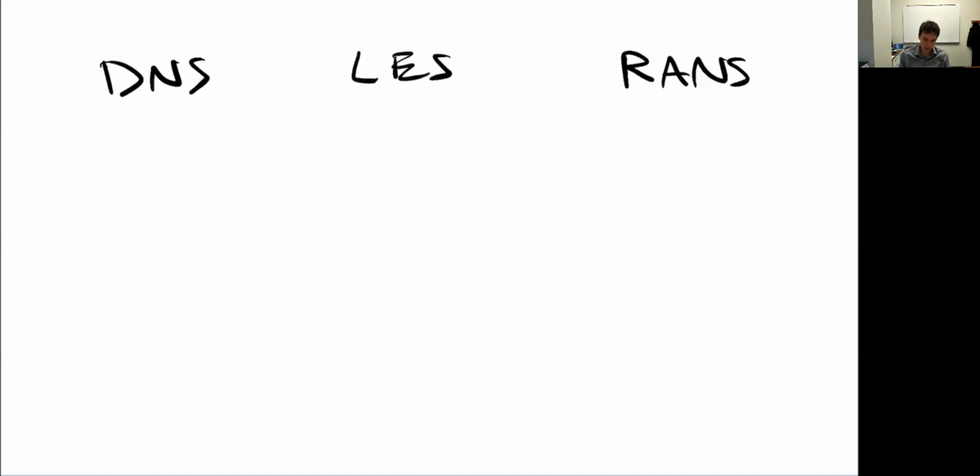The last thing I'm going to say briefly is something in between the two, right? So we talked about DNS, simulate all the scales. We said that's just impossible, right? Except for really low Reynolds numbers. RANS, let's forget about all the unsteady behavior, just average it all. Let's look at what's happening on the aggregate. Well, something in between the two is called large-eddy simulation.